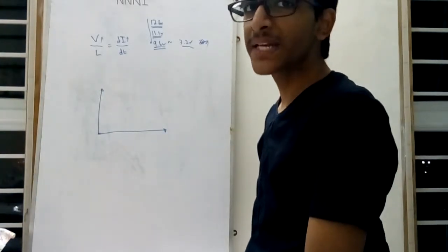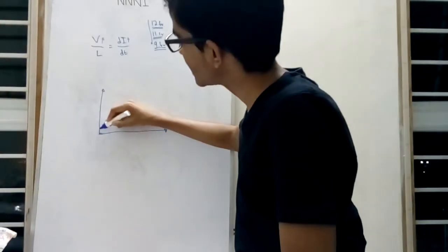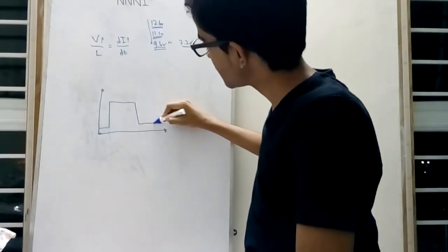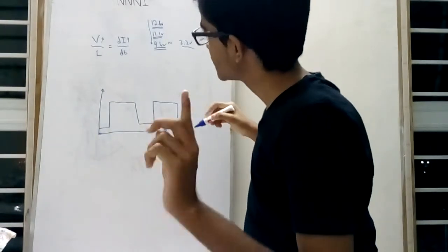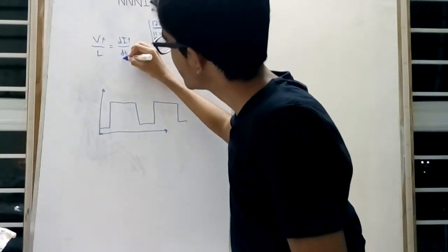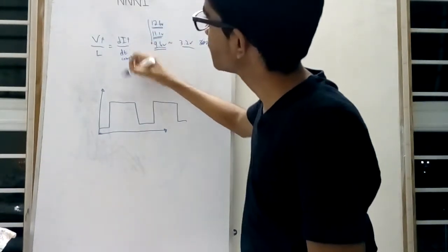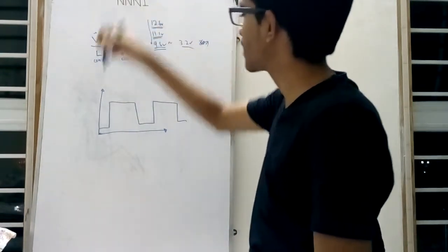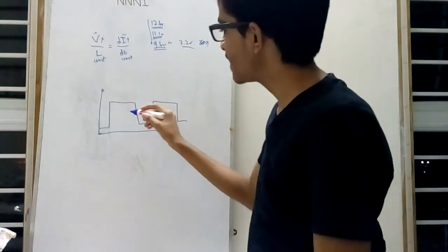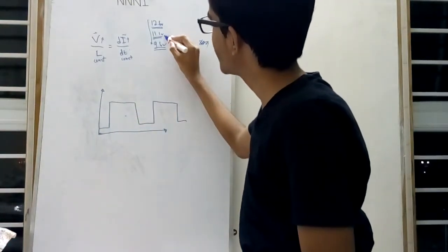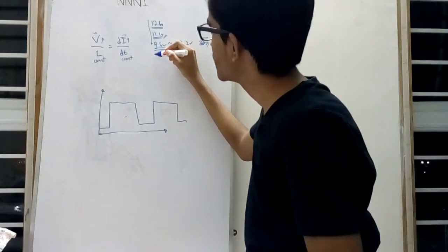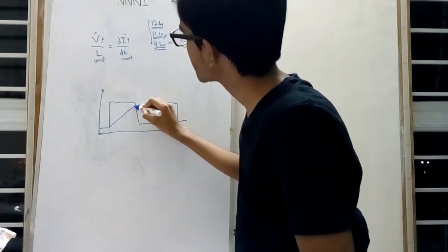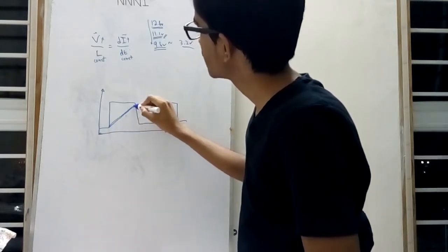So let's say you have a PWM source, for example a 555 that creates a square wave with a set time period. Highlight the word set over here. So dt is constant, your inductance is constant, and your voltage is changing, and so is your current. For example, you have calibrated this time period at 11.1 volts, which is the mistake I made. So at 11.1 volts, the current can rise up till the set value, in this case 5 amps.